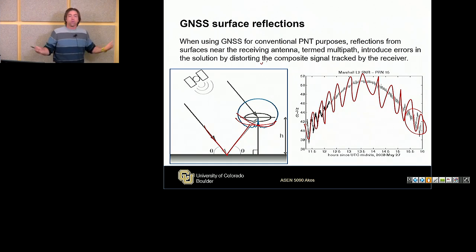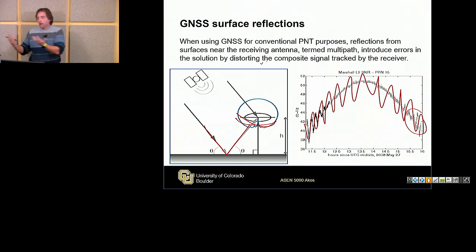But of course, it's not deployed everywhere. So what are you looking for? You're looking to try to leverage all the systems that are out there. You can get snow during that. But if you want to build a snow sensor and put it in remote locations, you can do it very inexpensively using these GNSS signals. So again, a concept that really wasn't considered anywhere before, but you can bring into play by thinking, okay, how can I use these error measurements and even tweak my receiver design to improve upon those pieces to see really what happens? So I think it's a very cool application.